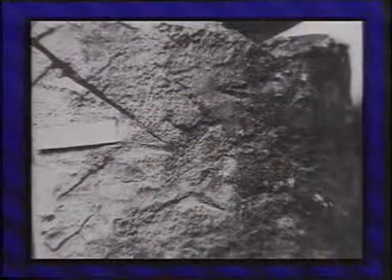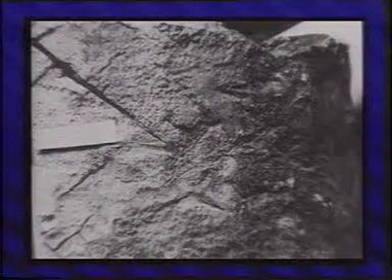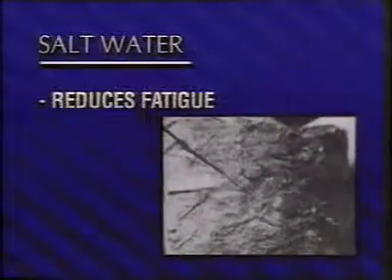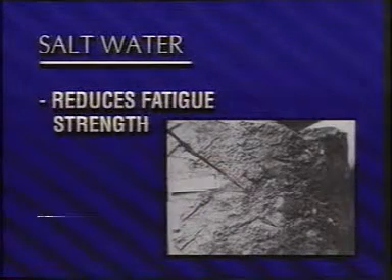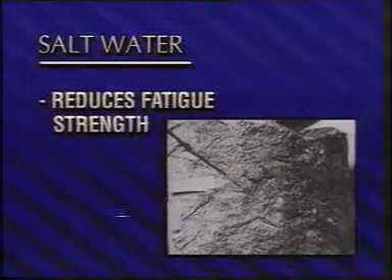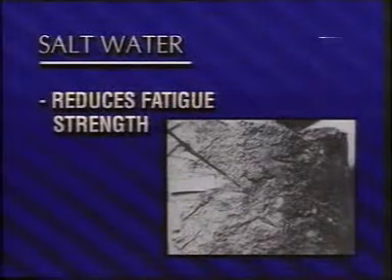Corrosion fatigue tests on smooth specimens of high-strength steel indicate that very large reductions in fatigue strength or fatigue life can occur in salt water. For instance, the fatigue strength at 10 million cycles could be reduced to as little as 10% of the fatigue strength in dry air.